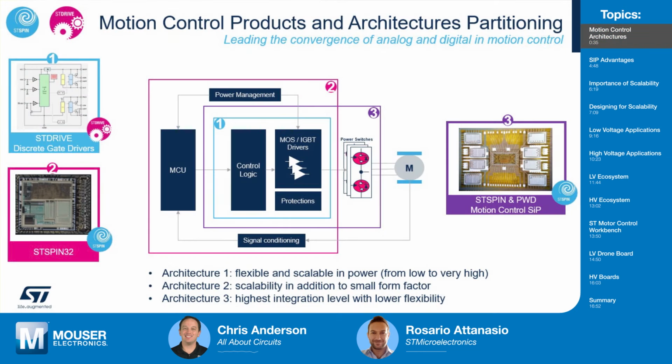So, what are some of the trends you see in the market? So there are many driving forces that are contributing to a real revolution in the power conversion arena. These driving forces are mainly efficiency, power density, and reliability. And more specifically, in the motor control field, we are seeing the adoption of integrated motor drives. The main objective of integrated motor drives is to make the drive electronics sufficiently small and rugged so that it can ideally be fitted into the housing of a motor.